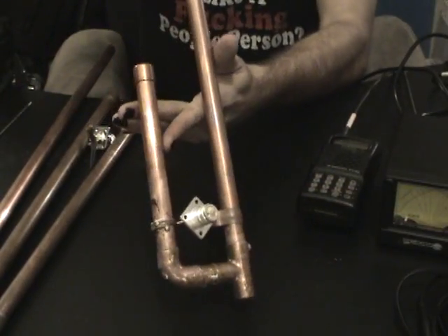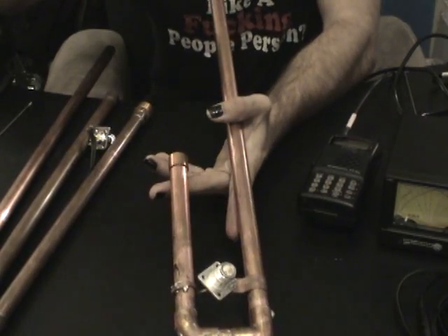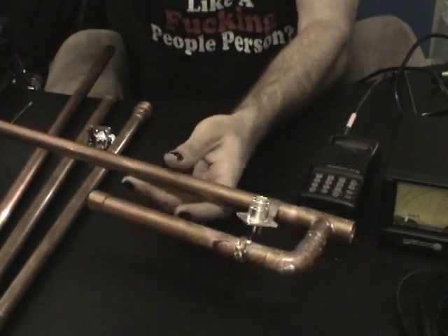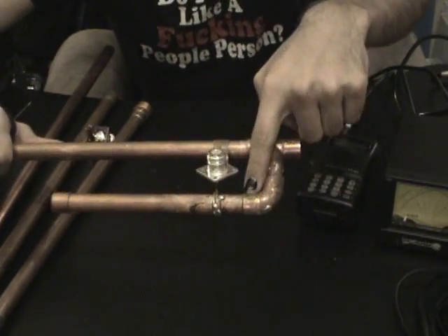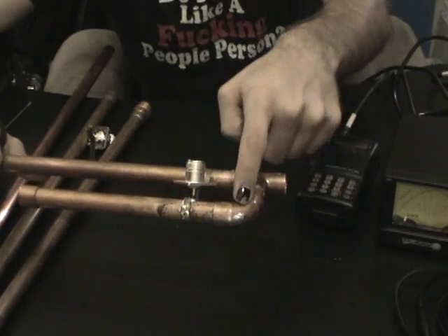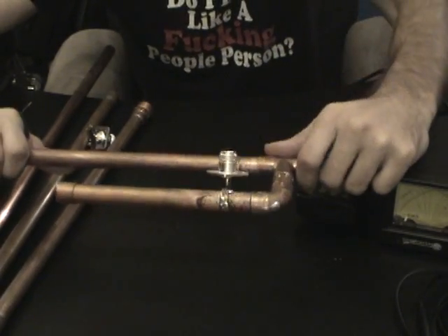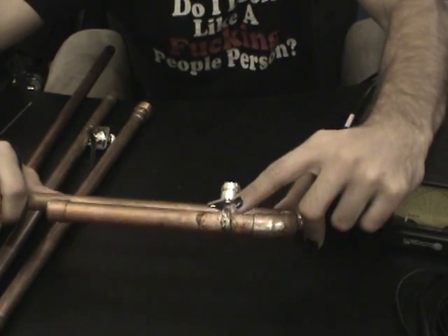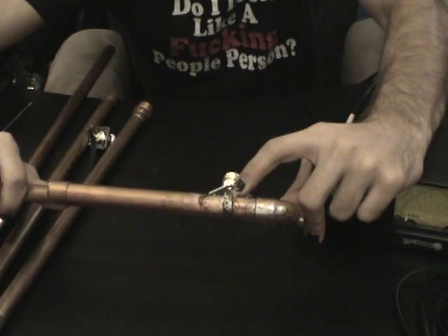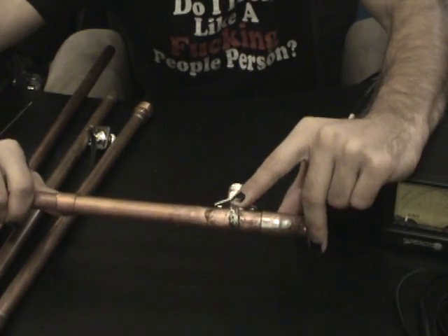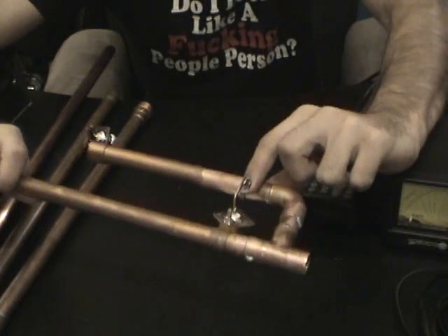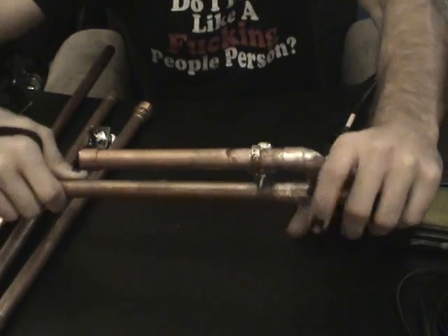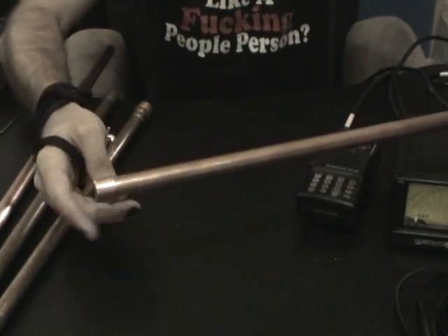For this J-pole, which is tuned to about 460 megahertz, what I did was I pretty much just sweat the appropriate connectors together, compensating for the bend radius of the T connector as well as the 90-degree angle elbow. I'm using a panel mount end connector, which is left over from our Wi-Fi series, and then I took some, I think this is 16 gauge copper wire, and I coiled it around a few times, and then attached it to the feed point per the instructions of creating a J-pole antenna, and I put spiffy little end caps.